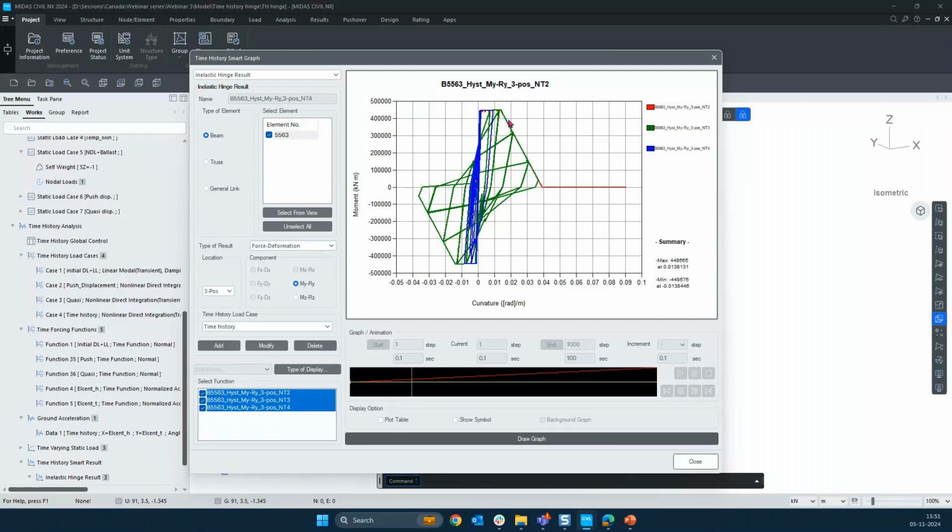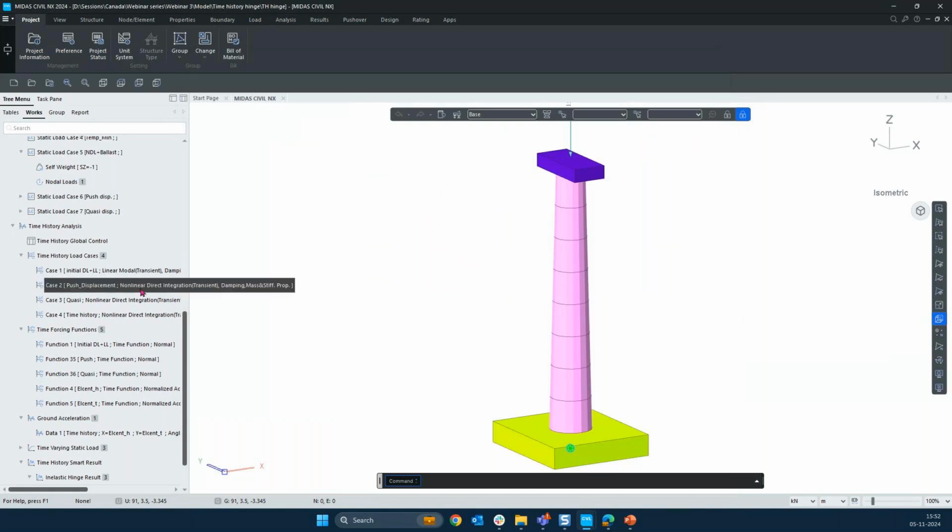So it means that the plastic pivot model that we have considered for the nonlinear record is adhering with the static pushover case for which the moment curvature curve was specified. Also, the blue color curve in here is basically the time history results that we got for this particular structure. And the loading and the unloading curves for this time history record are well within the inelastic moment curvature curve that we have specified for this model. So this is one of the verifications that we did.